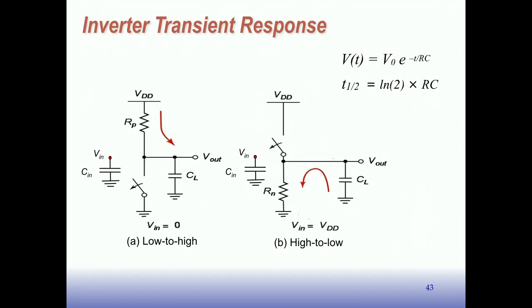So we had started out here where I showed you a common practice is to model the conductance of the transistors as resistances, and then consider the resistances in conjunction with the various capacitances. And for that, we can understand what the transient response for an inverter is. And of course, with this RC type modeling, the transient is exponential. So when we transition a node from 0 to 1, it's an exponential transition. And when we go from 1 down to 0, it's also an exponential transition.